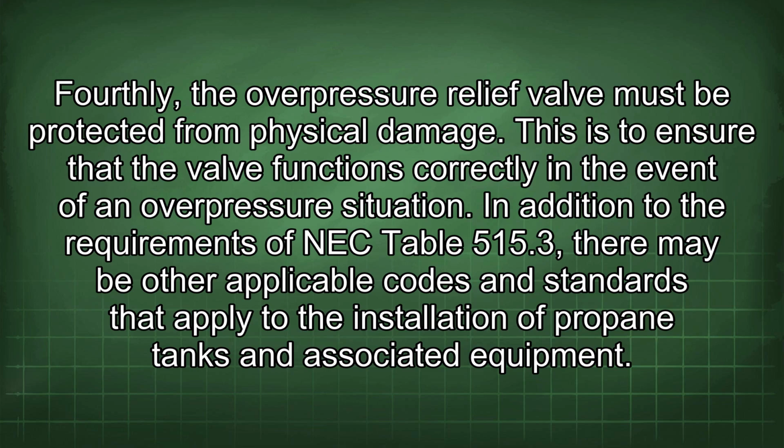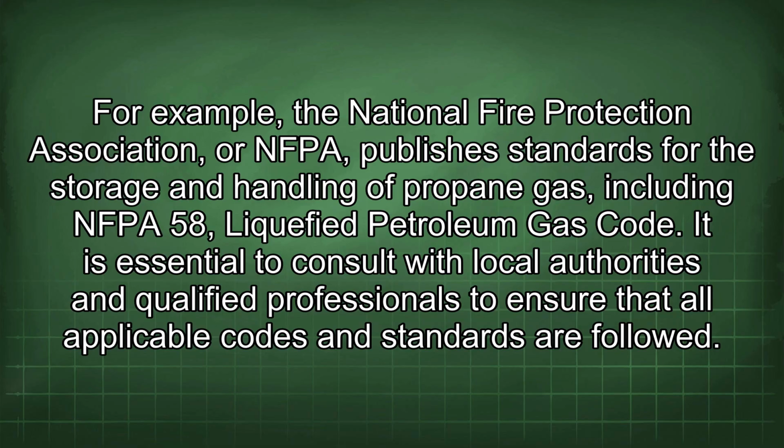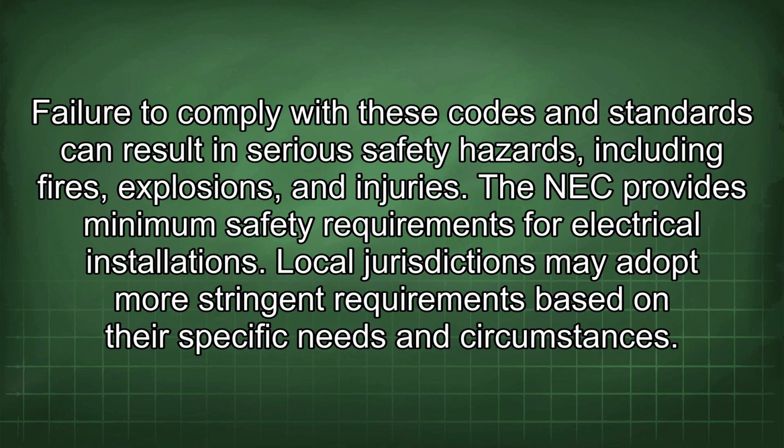In addition to the requirements of NEC Table 515.3, there may be other applicable codes and standards that apply to the installation of propane tanks and associated equipment. For example, the National Fire Protection Association, or NFPA, publishes standards for the storage and handling of propane gas, including NFPA 58 Liquefied Petroleum Gas Code. It is essential to consult with local authorities and qualified professionals to ensure that all applicable codes and standards are followed. Failure to comply with these codes and standards can result in serious safety hazards, including fires, explosions, and injuries.